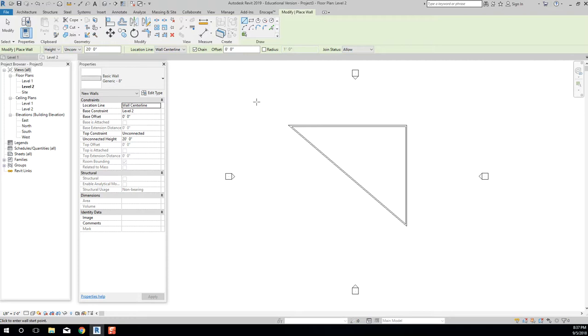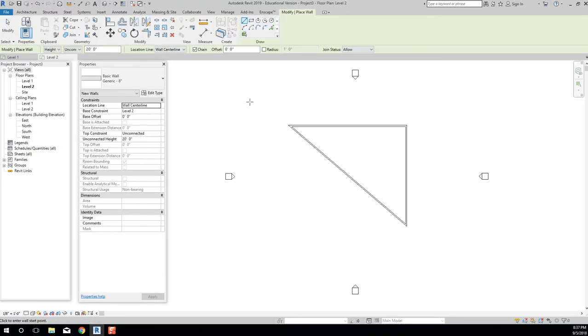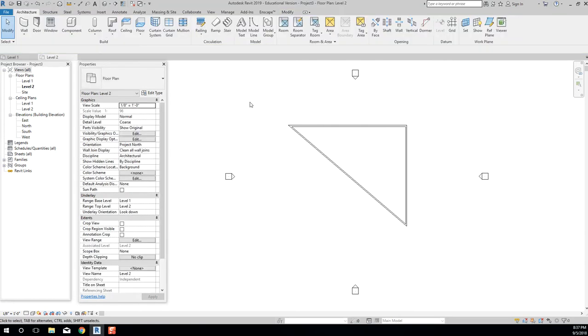In AutoCAD, you type something like L for line, enter, right? You type something else in, enter, enter. You're constantly hitting enter. With Revit, you just type WA and it initiates. That's it. There's no enter, right? If you hit enter, it'll make a noise. So we know that we're forgetting that we don't need to hit enter. So you very rarely will hit enter in Revit, okay? So I'm gonna hit escape, WA, there we are, escape, escape.